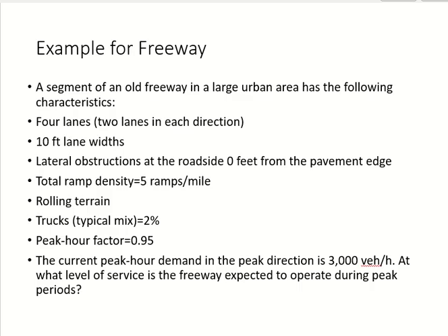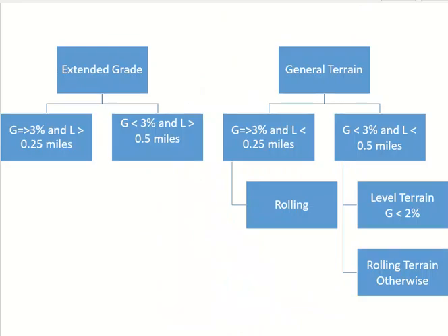First thing is you have to find out the free flow speed. Free flow speed for freeways. There are two equations, one for each type of highway. So this is the equation for freeway. There are three things in the equation. One of them is written with the question, which is what? TRD. So TRD is no problem. The other factors are for lane width and lateral clearance.